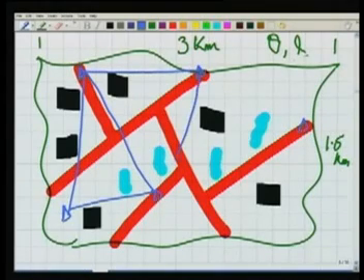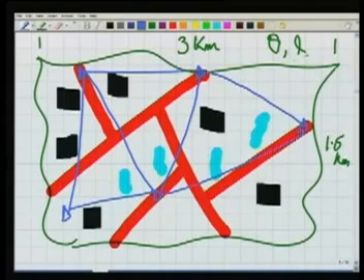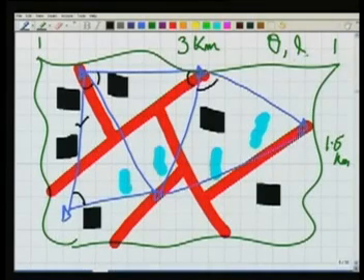So what we have done, we are making a set of triangles here. Now in this set of triangles, one length we want to measure accurately. So let us say this is the length which I measure accurately by spreading my chain or tape or by base extension method. As well as I am measuring all these angles now using the theodolite. Because measuring angle is not a problem, all these angles are also measured.